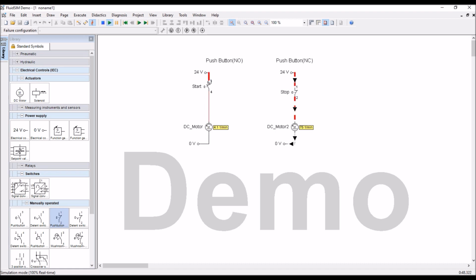But some applications will be having a long duration. So it is not advisable for the operator to hold the switch continuously because he cannot focus on other work. So in such applications, it is better to use toggle switch, but toggle switch you have to be very careful. If you use it, then operator has to come back to switch off. To hold the circuit, there is a holding circuit, using relay, we can easily do it. Okay, so let us explore the application of toggle switch. This is push button.